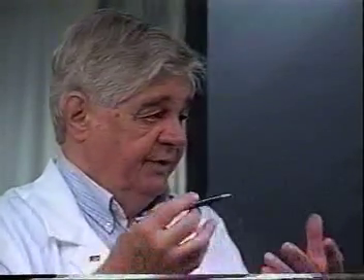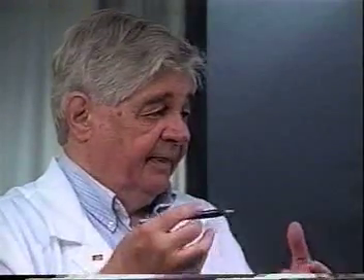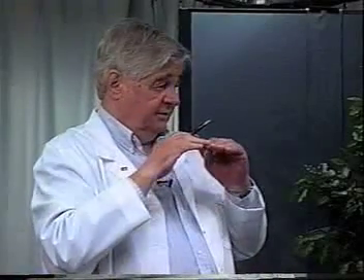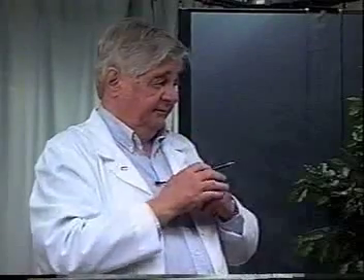The thermostat says, whoa, now it's up to 70 degrees, whatever we set it for, and it shuts the heat off. If it gets too warm in here, say we had the thermostat set for 70 and the temperature gets up to 75, it sends a signal to the heating and cooling system to turn the air conditioner on and cool the air down. As soon as the air gets back down to 70 degrees, it shuts it off again.